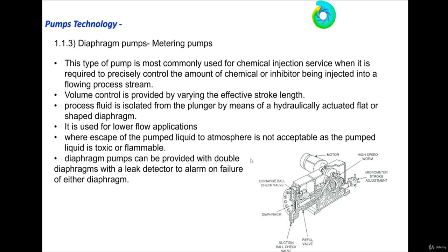This means that for the other types of pumps, the plunger, piston or rotary pump, the flow rate change may be more than 5% or 10%, or 3%. But for this pump, no. The maximum acceptable change in the flow during the linearity test of this pump is 3% as per API. The API used for this pump is API 675.